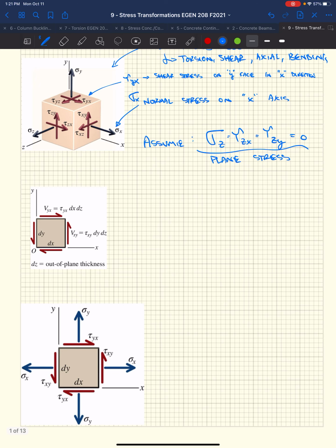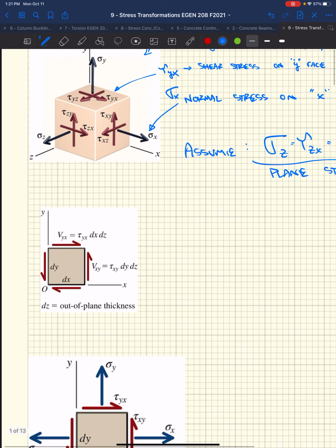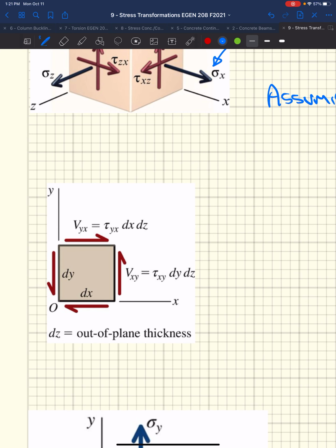We also need to know, if we start looking at plane stress, which we've already somewhat done in that previous example where we drew our stress block and there were no stresses on the outside of that pipe. We drew just a block and it had normal stress and shear stress. And we talked about how we figured out the stress on one edge of this block: tau max is torque times the max radius divided by the polar moment of inertia.